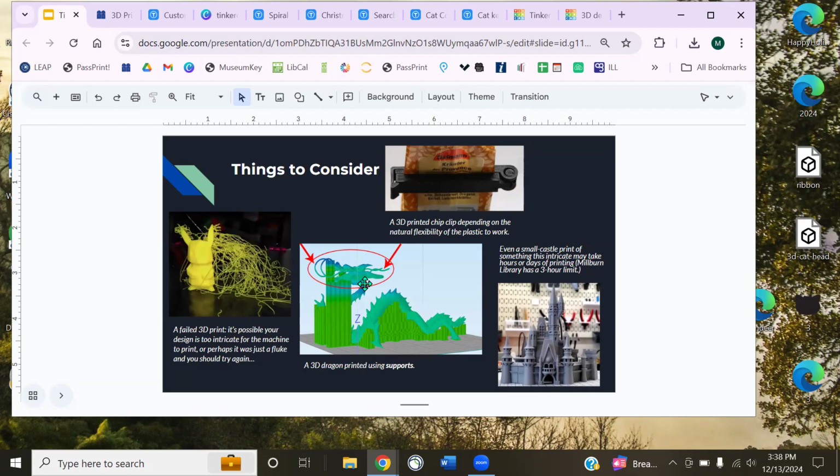And a couple things that means. One, if you do something that's a bit too delicate, like this dragon has kind of a delicate chin maybe, you do have to separate that scaffolding from the dragon head itself. So if the design is slightly too thin, then sometimes when you try and break away that column that's printed to hold it up, that can sometimes damage it. If it's too thin, it's just going to pull away the dragon snout itself.